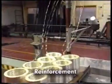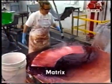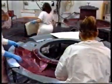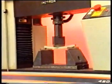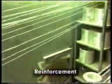and a reinforcement material. The matrix functions as a binder for the reinforcement and controls the physical shape and dimensions of the part. The primary purpose of the matrix is to transfer the load or stress applied to the composite to the reinforcement. The matrix also protects the reinforcement from adverse environmental effects. The reinforcement's function is to improve the mechanical properties of the composite and is typically the main load-bearing element.